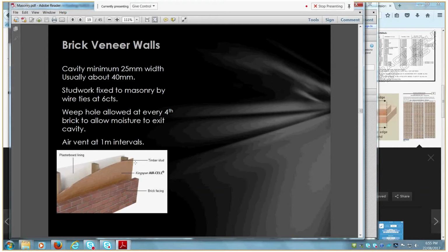very warm, moist air come into the house, and then it gets cold at night, and moisture condenses. And your plasterboard or plaster linings inside the house take up that moisture, and they regulate the moisture within the room. If you were to use blue board as internal linings, you end up getting moisture collecting on your internal linings, and you get mold, etc. happening as a result of that. So that's typically why we use some form of plaster, be it gypsum plaster or so, for internal linings.